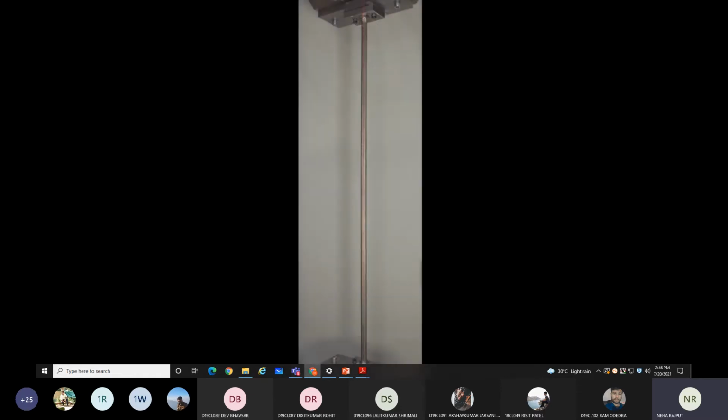The testing rig is now starting to apply a compressive force to the specimen. We can see the top end displacing and the column begins to deflect sideways as a result of a structural instability, which is better known as buckling. The profile of the column as it buckles is theoretically a full cosine wave. Note that the column ends do not rotate due to the fixed-ended conditions.